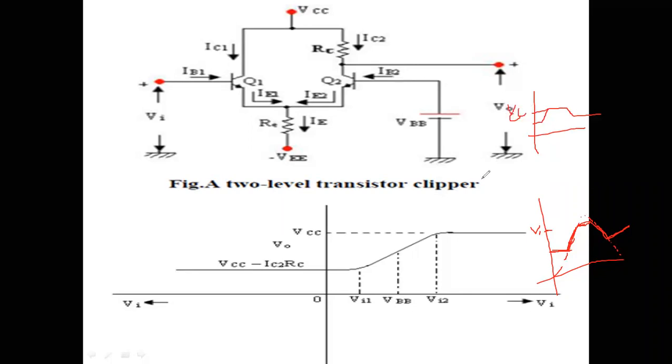Here we should not get the doubt about VCC being greater than the input voltage. Suppose VCC is 3 volts, and the input voltage is 10 volts. That means input is 10 volts, this is your input voltage, your peak value is 10, and your VCC is 3 volts. Therefore, above the 3 volts is going to be clipped. Above the 3 volts, you are going to get clipping.